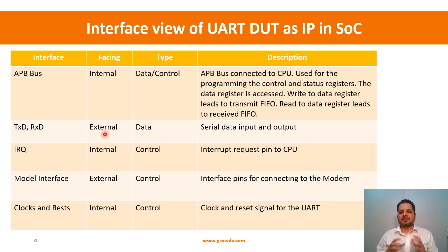What do I mean by that is that if we put this UART IP inside a SoC, then there will be these 2 pins, right? So these 2 pins will definitely come out of the package. So if somebody gives us the spec of the package, the spec of the chip where the UART has been used, in the port list we will be able to see these 2 pins. You will see TXD and RXD pins, right?